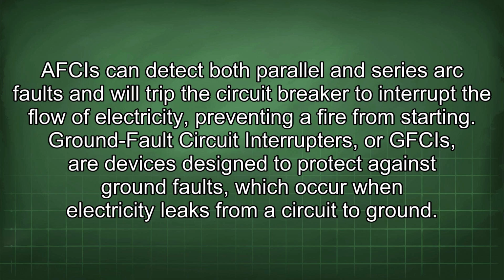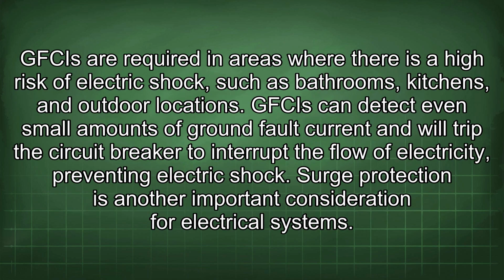Ground fault circuit interrupters, or GFCIs, are devices designed to protect against ground faults, which occur when electricity leaks from a circuit to ground. GFCIs are required in areas where there is a high risk of electric shock, such as bathrooms, kitchens, and outdoor locations. GFCIs can detect even small amounts of ground fault current and will trip the circuit breaker to interrupt the flow of electricity, preventing electric shock.